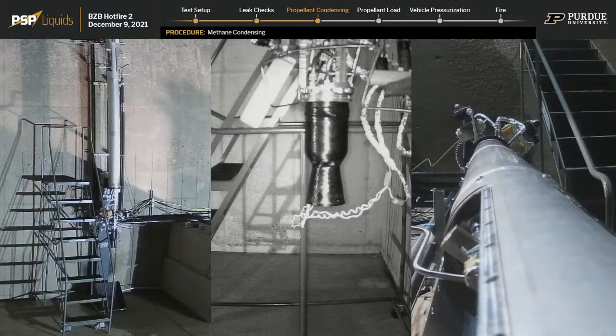Wrapping our TCA in carbon fiber dramatically reduces the weight of that component, and it's really just one of the ways that we can exploit a mass advantage on our system. Mass is one of those things that we have to optimize for at every stage. That's why everything's aluminum 6061. That's why we have a lot of different pressure sensors that are taken on for testing, off for flight. That sort of stuff is what we're really doing.